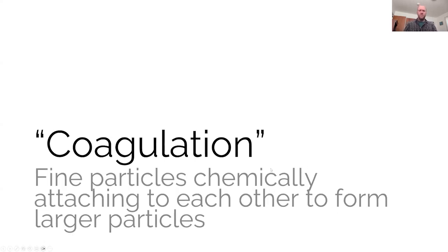Okay, and coagulation, you'll notice that this term was actually in that definition of flocculation. Whereas flocculation is the physical clumping of particles, coagulation is the chemical clumping together of particles. So in wastewater, as well as in drinking water, most of the stuff coming in has a negative charge to it, and so it usually separates, it doesn't want to clump onto each other.